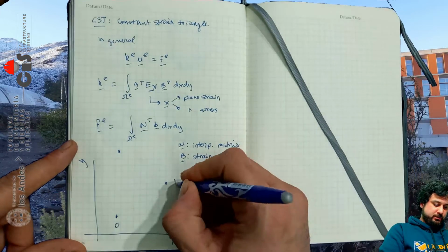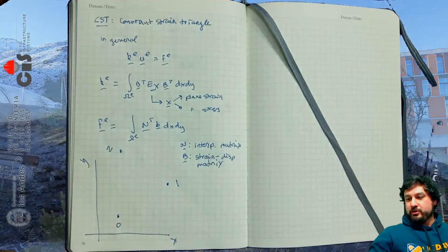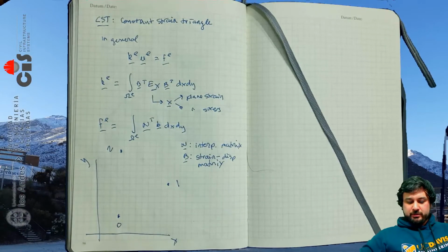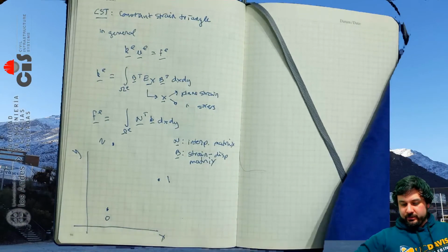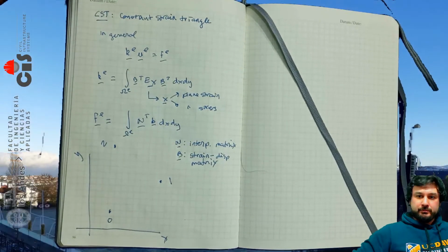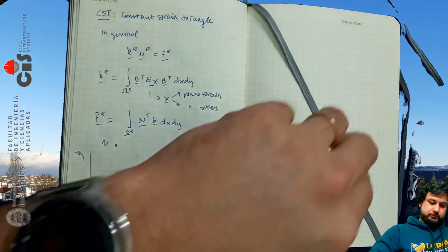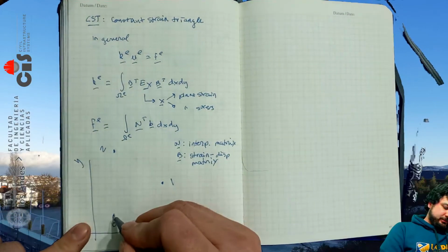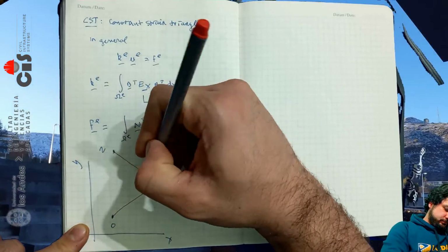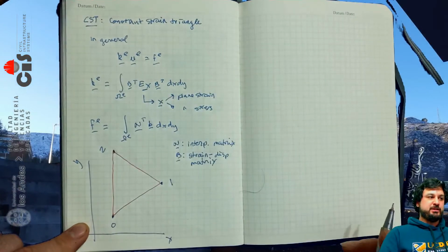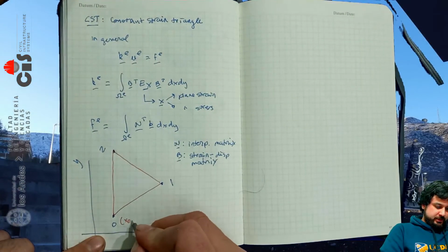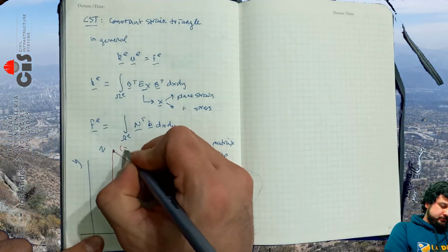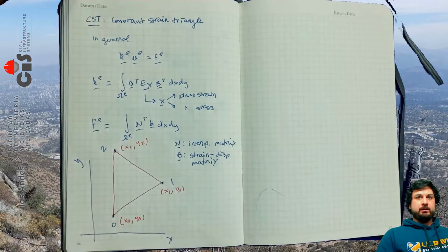So this is going to be point 0, 1, and 2. I start from 0 because the implementation of this is going to be in Python, so it's going to be comfortable if we have everything in the same notation. With those 3 points, we define a triangle specified by the corners. At each corner you're going to have the x, y coordinates of that respective node.